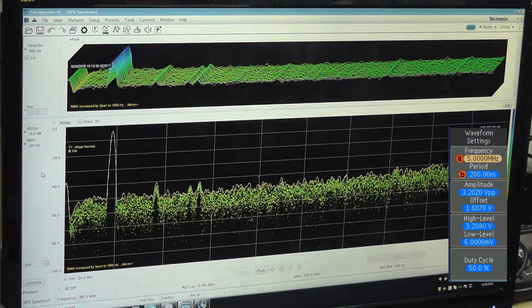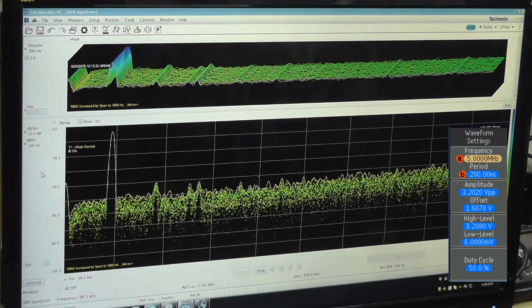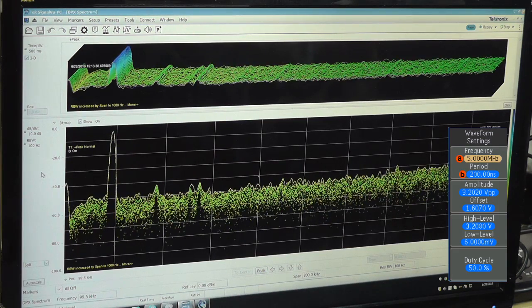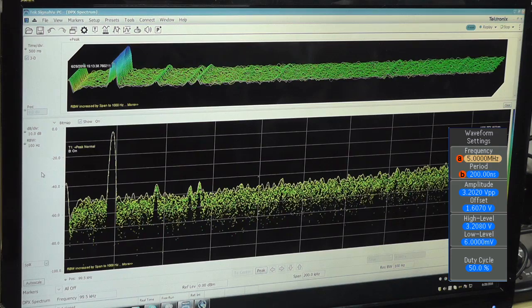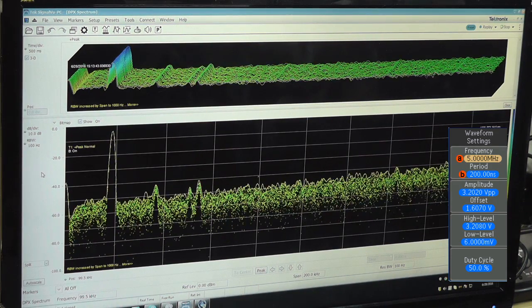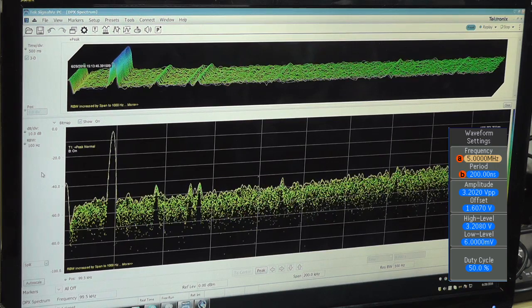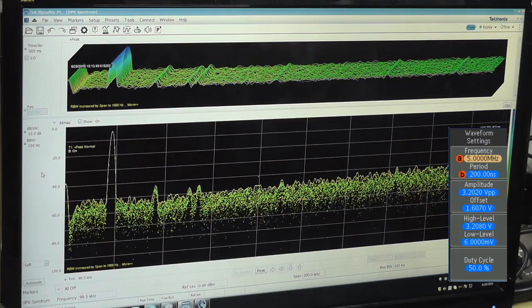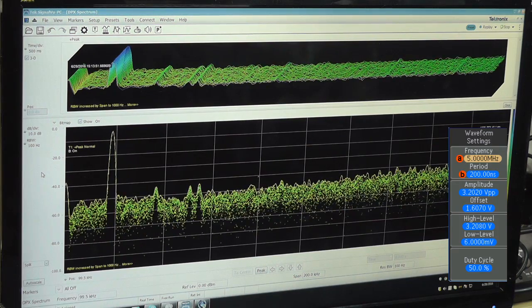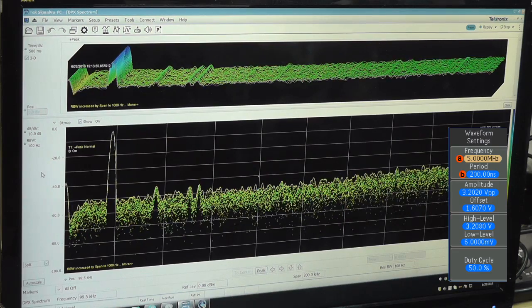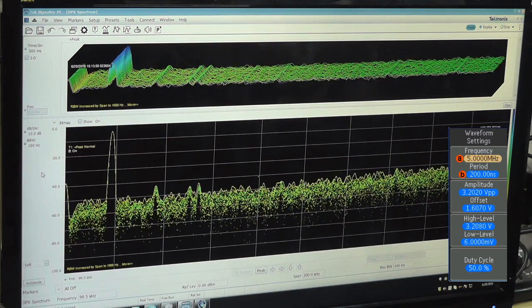All right, back in the frequency domain. Remember, to the left is a low frequency, to the right is a high frequency. And this is a spectrum analyzer that shows us this. This is running an FFT, a fast Fourier transform, to display this. And then I've got a signal generator hooked up. And remember what we said, that oversampling by 4 gets us another effective bit of resolution. In other words, approximately 6 dB.